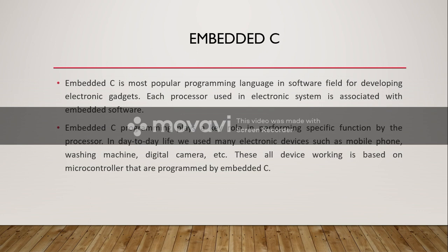All these devices work based on a microcontroller and are programmed by embedded C. Embedded C typically requires a non-standard extension to the C language in order to support enhanced microprocessor features such as fixed point arithmetic, multiple distinct memory banks, and basic input-output operations.